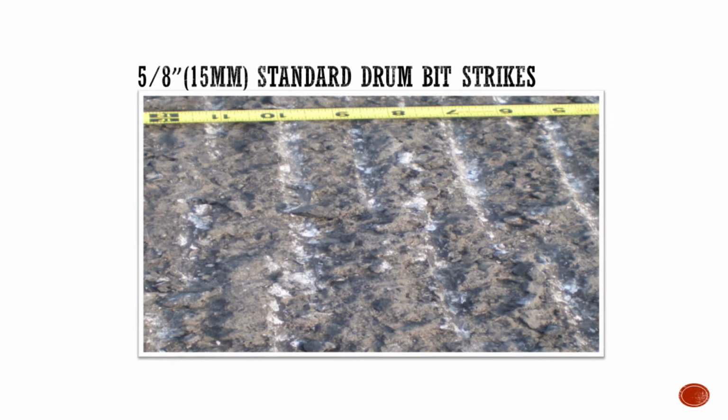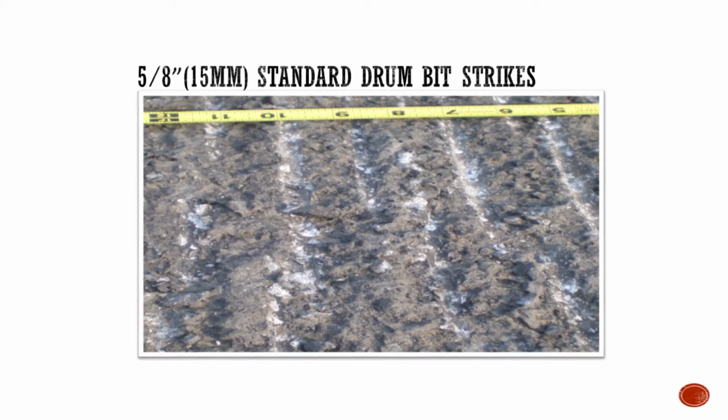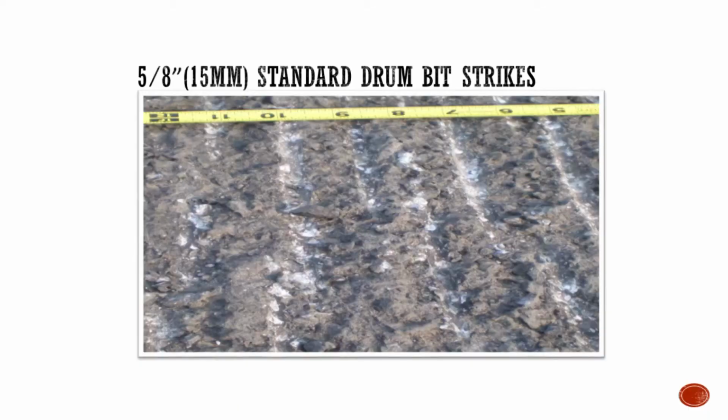Check out forward cutting speed and how it factors into the equation. In this image, it goes back to a 5/8 of an inch standard milling drum. You can see that you only have the 5/8 of an inch spacing on the ground in this little tiny area. From this pick to this pick right here, that's 1.25 inches. And then you see 1 7/8 inches. So in the larger section, you just see a little bit of the 5/8 of an inch. You actually only see 5/8 between this little section.